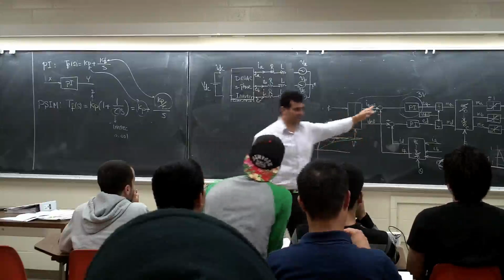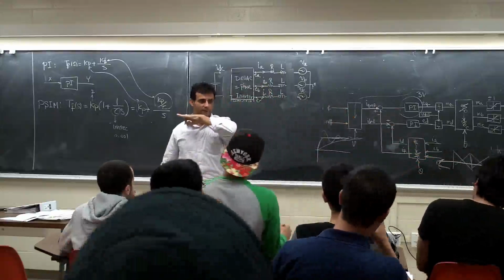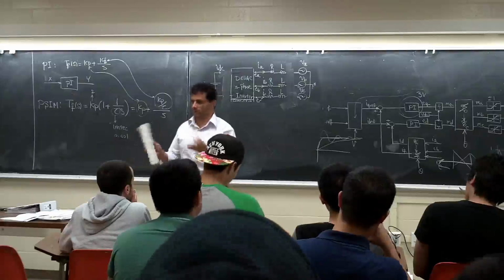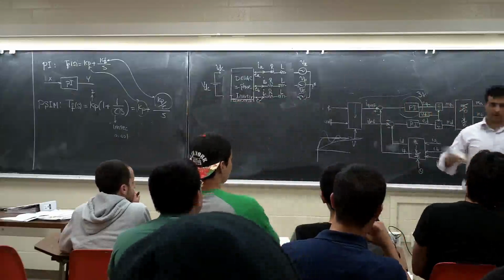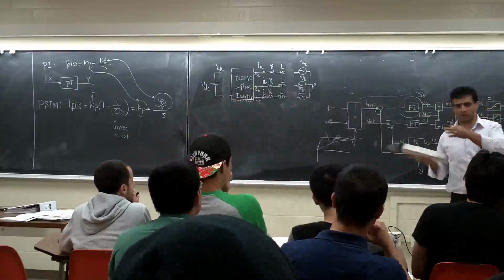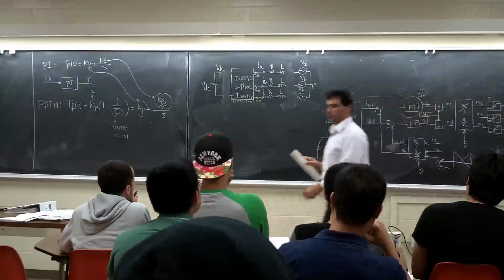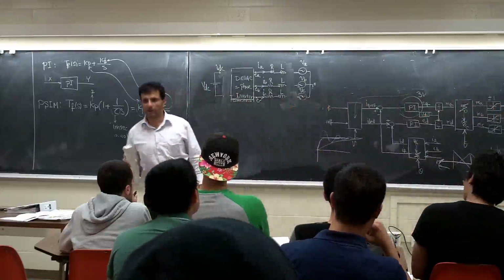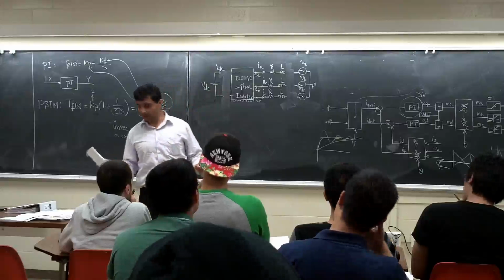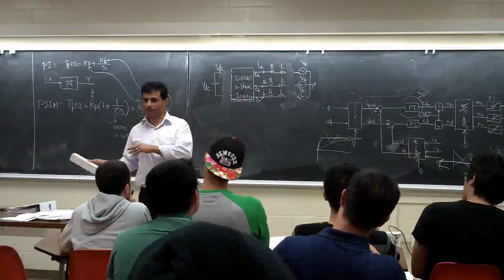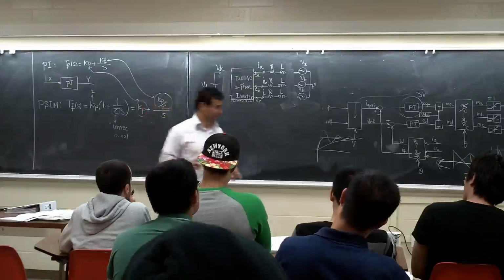But if we simulate this system, you can see when you change your P ref, your Q is also going to change. They are kind of coupled together. When you change this one, it is going to start to oscillate. Again, it's going to get kind of tuned, but there is some transient. We are going to talk about the decoupled control of active and reactive power. Decoupled means when I change my P, hopefully my Q doesn't change. By Q I mean reactive power. When I change my reactive power, hopefully my P doesn't change, it stays. We call it decoupled control of active and reactive power.